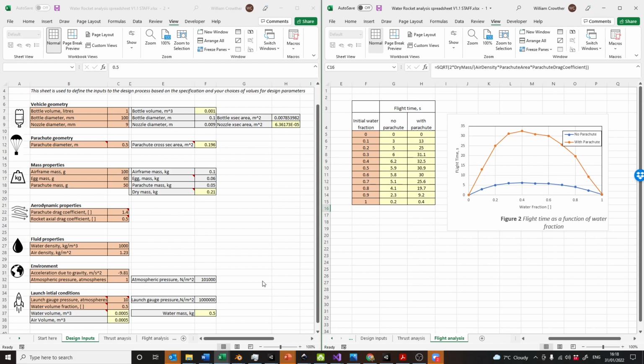So things like launch pressure, you don't have a lot of control over. The rocket's going to explode anything much above a launch pressure of 10. But things like drag and things like mass do make a difference, and you can control that. So when you're slapping on extra layers of tape, or you're putting on a very heavy nose cone or the like, you can think, actually, what difference is that going to make?